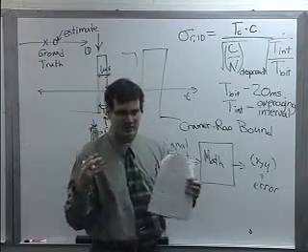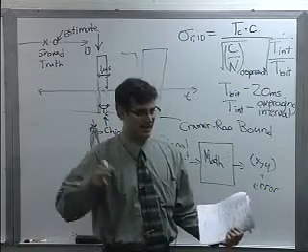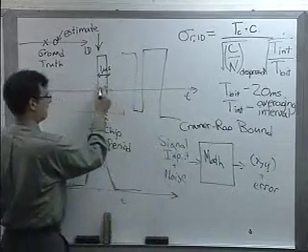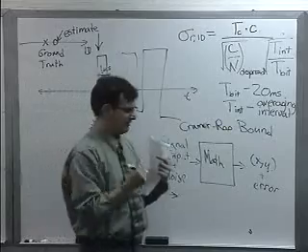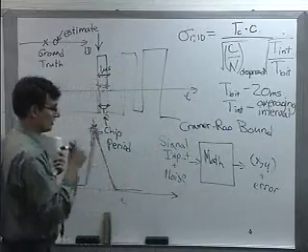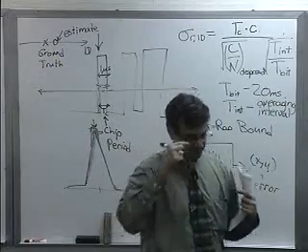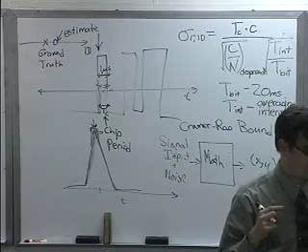And that's basically temporal superresolution, if you've ever heard that term. It's averaging again and again and trying to pin down very precisely, far within a chip period, when the true time of arrival was for this signal. People try doing this in the cellular industry for E911 location. That was always a bad idea.